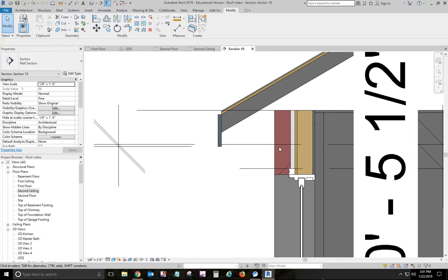Okay, because I'm going to have a 1x6 fascia board right here that comes up to the bottom of the soffit, and then the soffit comes out to there, because all of the detail sheets show that sticking out, whether it's on top of the face brick or against the wood seating. They all have that.